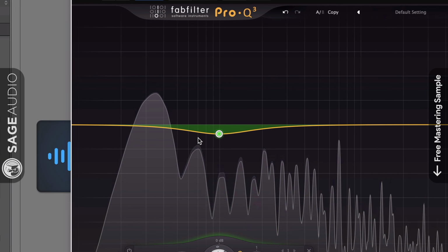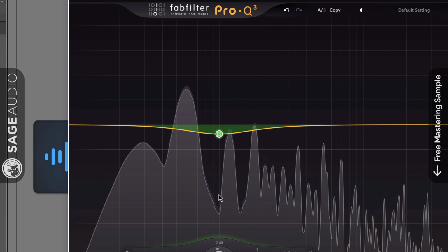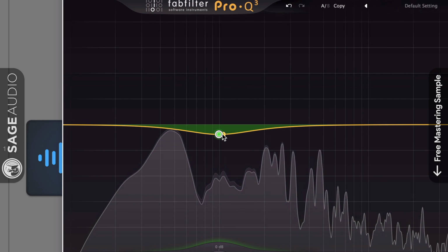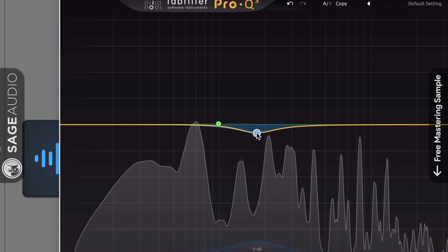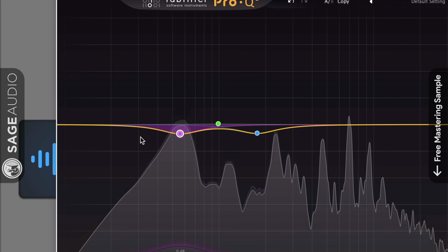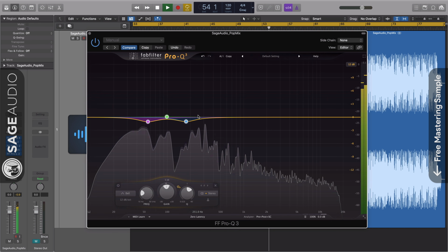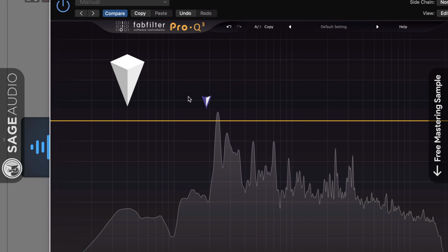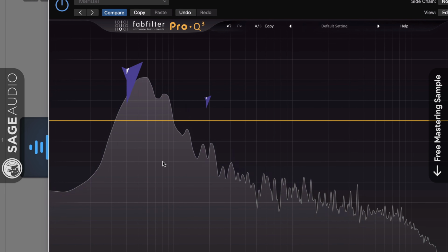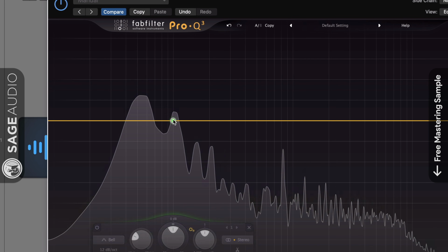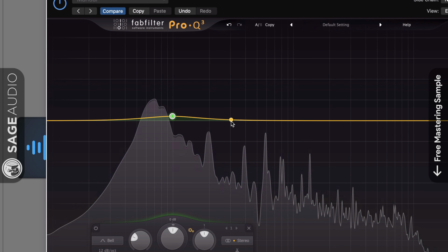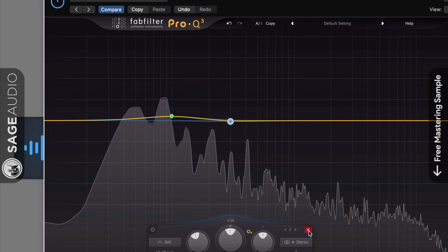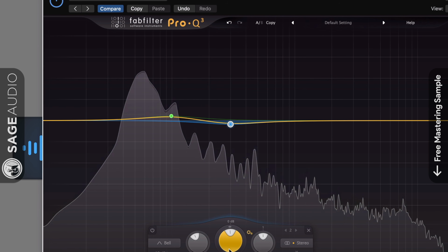Equalizer bands work by inverting the phase of a part of the signal and then combining it with the original signal in order to attenuate it. That said, understanding phase relationships can be a big part of understanding subtractive equalization. Now, the primary thing to consider is how lower frequencies mask or cover up the frequencies directly above them. For example, a 100 Hz wave will mask some of the amplitude of a roughly 300 Hz wave, and so on. As you can imagine, this makes that 300 Hz wave a little less perceivable.